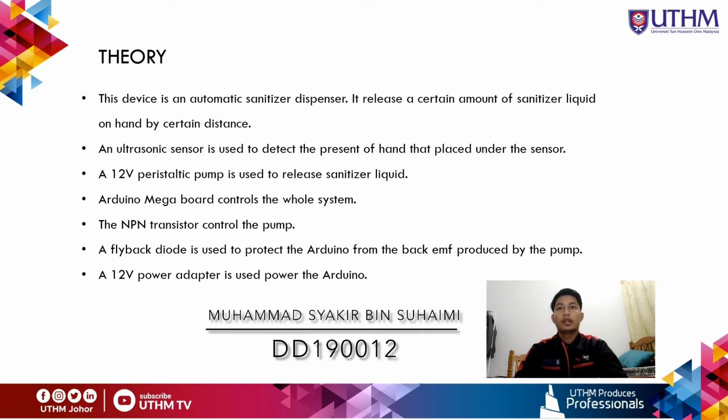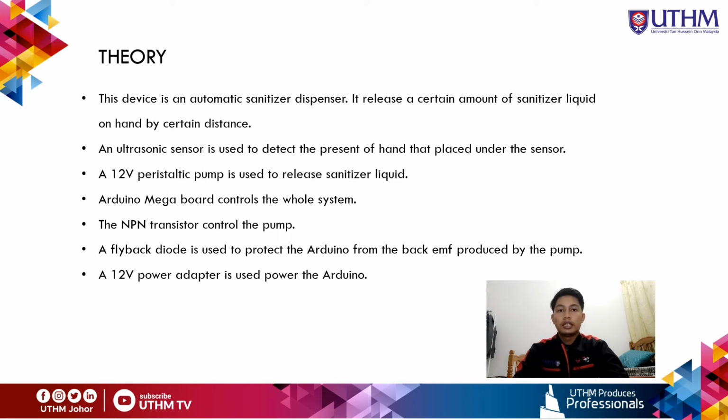So for the theory part, this device is an automatic sanitizer dispenser. It releases a certain amount of liquid on the hand at a certain distance. It has an ultrasonic sensor which detects the presence of a hand placed under the sensor. Then it has a 12 volt peristaltic pump, used to release the sanitizer liquid.